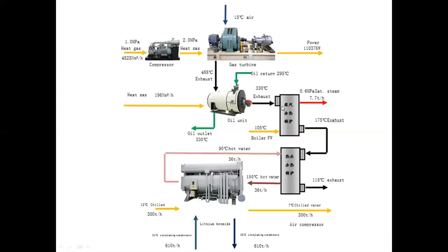Okay, but we're not done yet. Their exhaust is now down to 175 C, and they're going to put it into a hot water generator. They've got 90 degrees C hot water, return water. That's the cold water coming back, and it's going to be heated to 130 C. This is going into an absorption chiller, which is a refrigeration device that runs on heat.